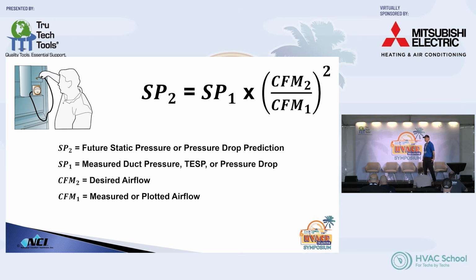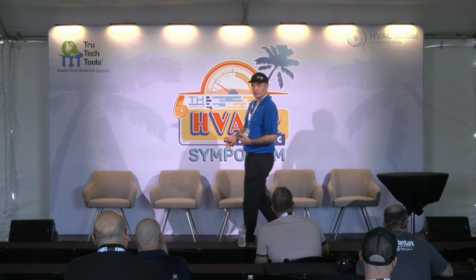So when would you use this? Well, let's say you have a system that has low system airflow, right? And you're measuring your static pressures, and they're not terrible. Have you guys ever replaced a system? Let's say you have a 3-ton system with a PSC blower motor, and you install a new furnace with a variable speed motor on it, and then you start commissioning it, and the thing sounds like a rocket ship gonna take off, right? And your static pressure is through the roof.